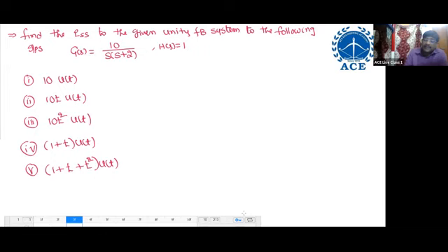Okay, I'll write the answer. Listen. What is the type of the given system? The type of the given system is 1. That means only for the ramp input you will get a constant. The remaining are all either zeros or infinity. Type 1 means you will get a constant steady state error for only the ramp input. The remaining are zeros or infinity. Now come on, calculate ESS.